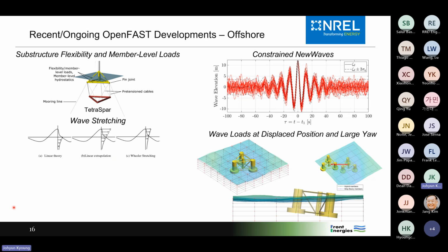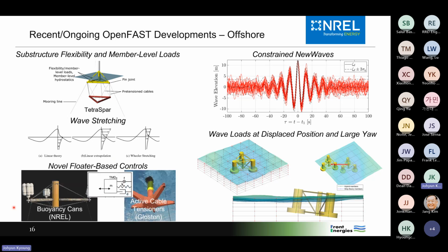And then coming out here in 4.0 is a big change, including the introduction of our new sea state module. We basically now have a full 3D wave grid where the structure will float inside it. And that really gives us the ability to do the proper phasing of waves as you have large displacement. Right now, in 4.0, you'll get that release with large surge and sway motion.